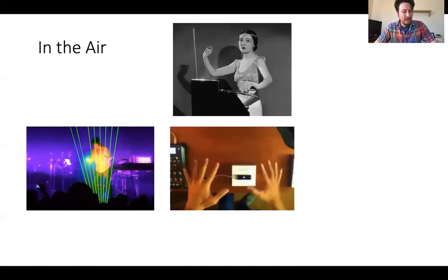A more detailed set of laser beams comes in the form of the technologies behind the Leap Motion and there's a game system, Microsoft Kinect. These devices send out invisible infrared laser beams in all sorts of directions, and then use the reflection data off of that to determine things like hand position, orientation, number of fingers that are sticking up. In the case of Kinect, it's mapping your entire body. So like hand position, proximity, and this stuff is all figured out, calculated within the firmware or the host drivers. So it's giving you pretty cool detailed orientation.